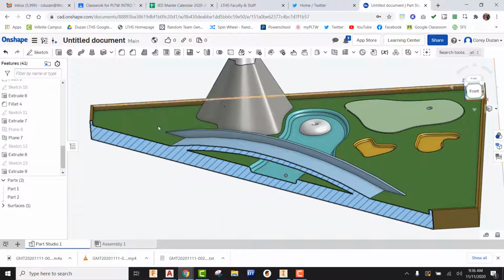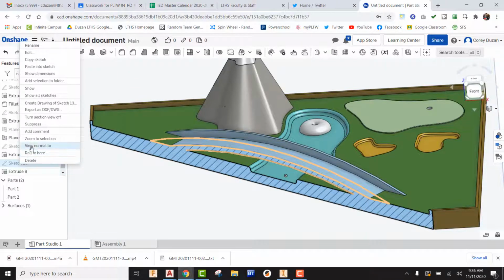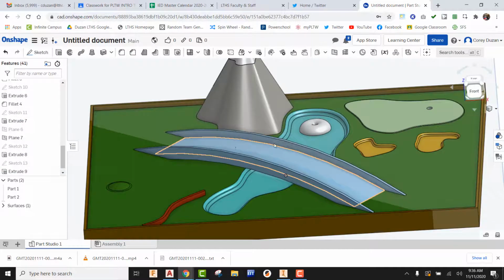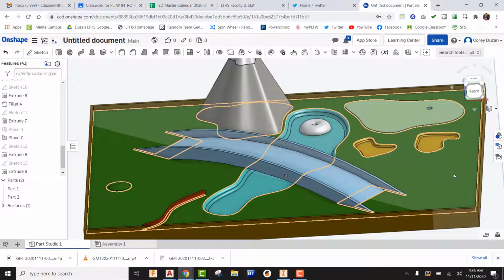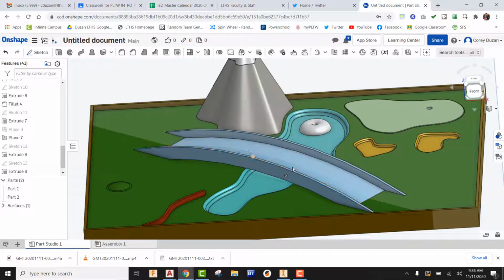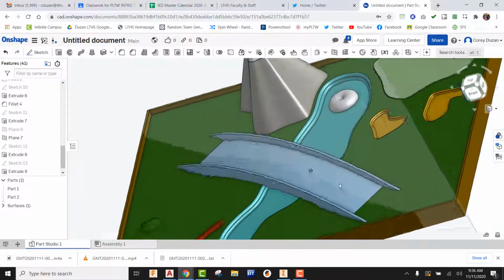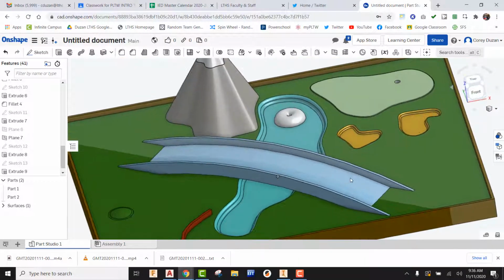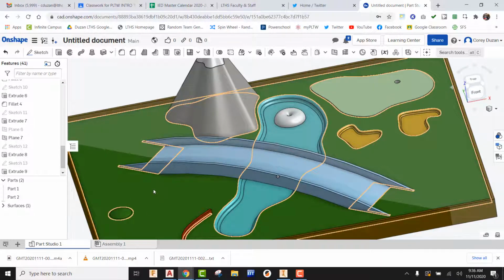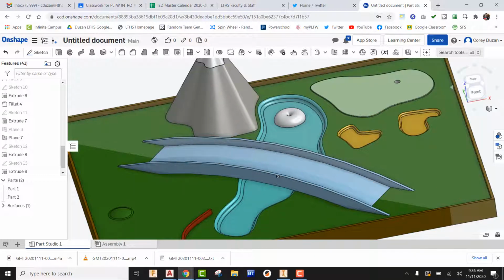Okay, when I green check this and come back into my sketch to turn off my section view, you're going to see now I've built that rail in. So it was 2 symmetrical extrusions. One was an add, the other one was a remove. When I do that, you're going to see how I've given the walkway. I've also given a rail, so a little bit of safety factor, and it makes the game a little easier. But that is how you would create a bridge. You don't necessarily have to create the rails on this, but I think it's helpful for a lot of people, so that's what I would go with. All right, so that is how you create a bridge for your mini golf course project.